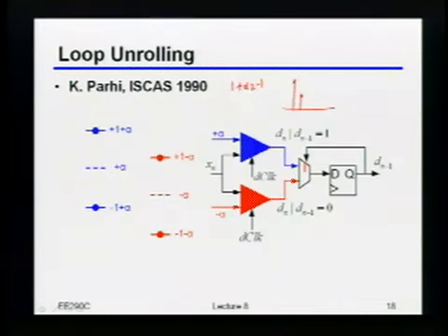Okay? So just to clarify what these diagrams are showing you, if you have a channel that looks like this, where the main tap is just 1, and the second tap, or the post-cursor tap, is alpha, that's saying there are 4 possible levels you can get, right? Because even though my main thing is plus minus 1, I'm always going to get a plus minus alpha from the previous bit. In other words, with 2 bits, there are 4 possible combinations you can get, okay?